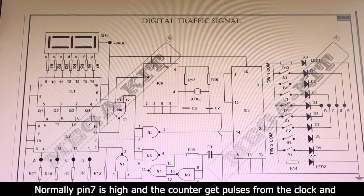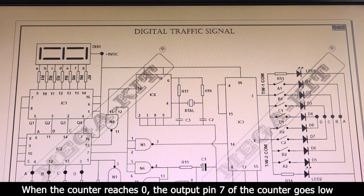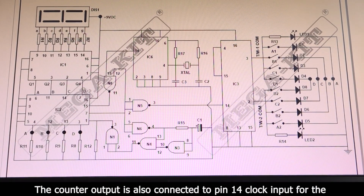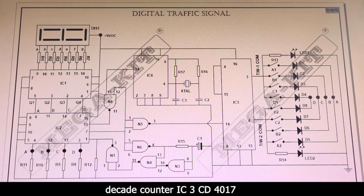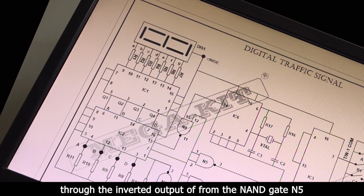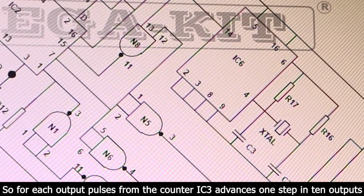Normally pin 7 is high and the counter gets pulses from the clock and it starts counting down. When the counter reaches 0, the output pin 7 of the counter goes low, so the clock pulses will stop reaching counter input pin 15 of IC2. The counter output is also connected to pin 14 clock input for the decade counter IC3 CD4017 through the inverted output from the NAND gate N5. So for each output pulse from the counter, IC3 advances one step in 10 outputs.